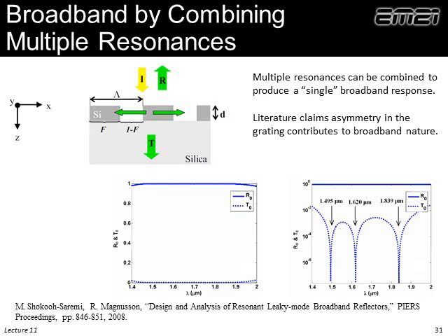So before, I described this multiple resonance thing as bad, but in fact we can use this, and people are becoming very good at designing multiply resonant GMRs to get an overall broad frequency response. And folks are also doing this, we are doing this, combining multiple resonances to also make it wide field of view. So our guided mode resonance filter can accept waves over even just a 40-degree swing of angles, and that's huge. Typically guided mode resonance filters have to be less than a degree. But now we've designed devices that work the same way over a 40-degree field of view. That's pretty amazing.